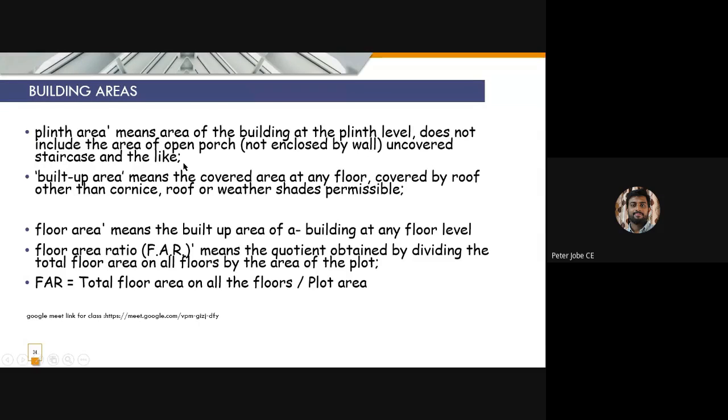If our staircase is inside our building, we will include that in the plinth area. But if the staircase is provided outside the building, we won't include that in plinth area. So plinth area does not include the area of open porch and other open structures. At the plinth level, we'll draw a plan and find out all the things which are enclosed. We will take all those things as the plinth area.